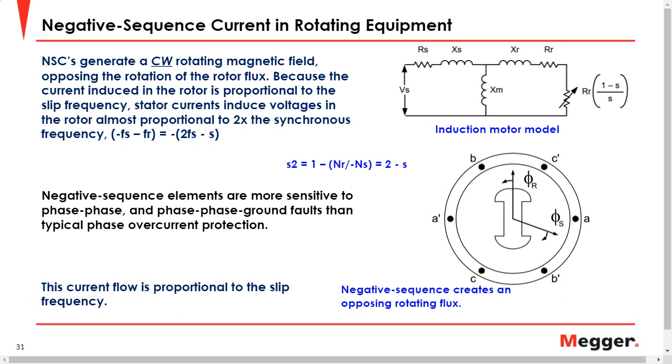Another thing that can contribute to this, even though it's a three-phase balanced fault on the system, is that our bottleneck is really how we are detecting this. How are we bringing this data in? That's through our instrument transformers, our CTs and our PTs. There is a standard tolerance associated with each of those, but there is still a built-in percentage of error that's going to occur.